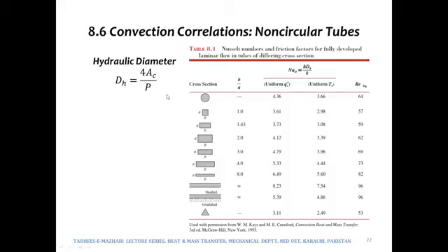Over here we must discuss a very important concept, which is called hydraulic diameter. Now, hydraulic diameter is given as this thing, 4 times cross sectional area over wetted perimeter. This is called wetted perimeter. So the hydraulic diameter concept is used in several cases, for example, in non-circular cross sections as well. We need to discuss hydraulic diameter in a bit of detail.